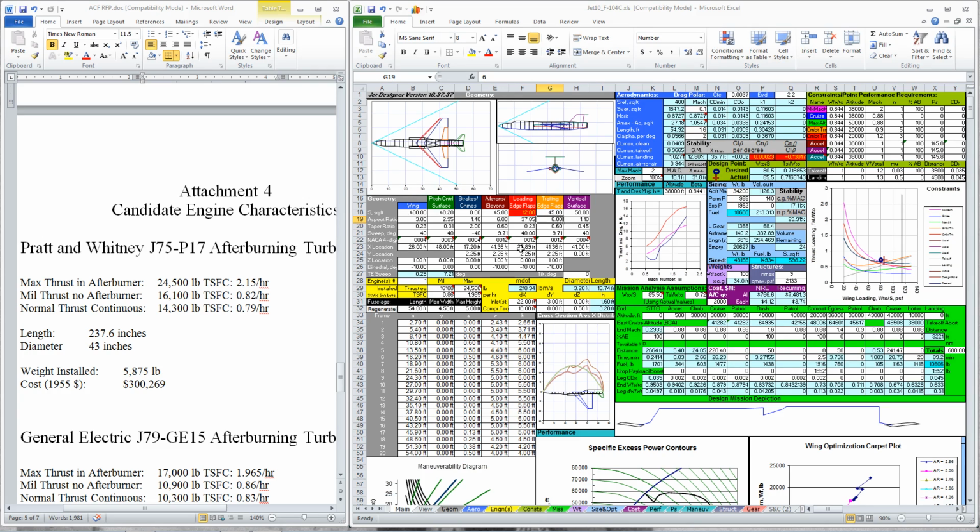This says that our leading edge flaps need to be big because we have a supersonic leading edge at the maximum Mach number. So our leading edge needs to be sharp, so we have to have leading edge flaps. And that's okay, we can do that. They need to be at least half as big as the flaps on the wings. Maybe we'll even go higher aspect ratio 7. That'll give us a little more roll control. That looks pretty decent. Not that different from an F-16 wing.